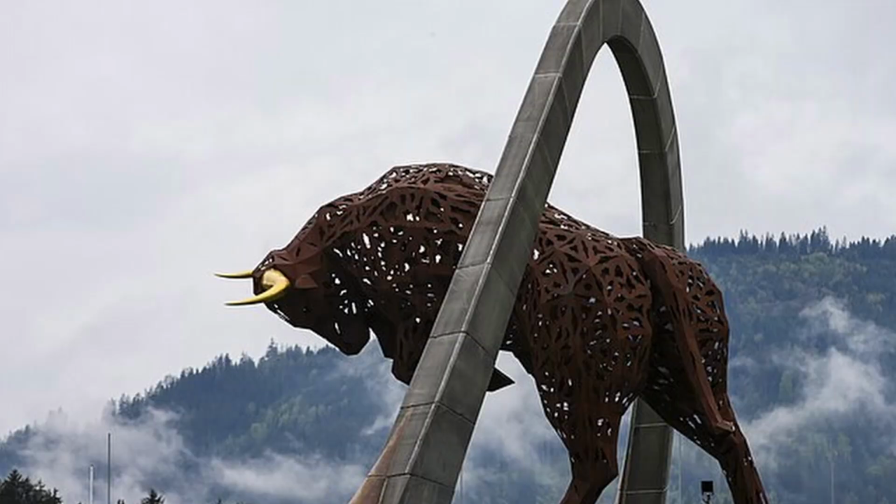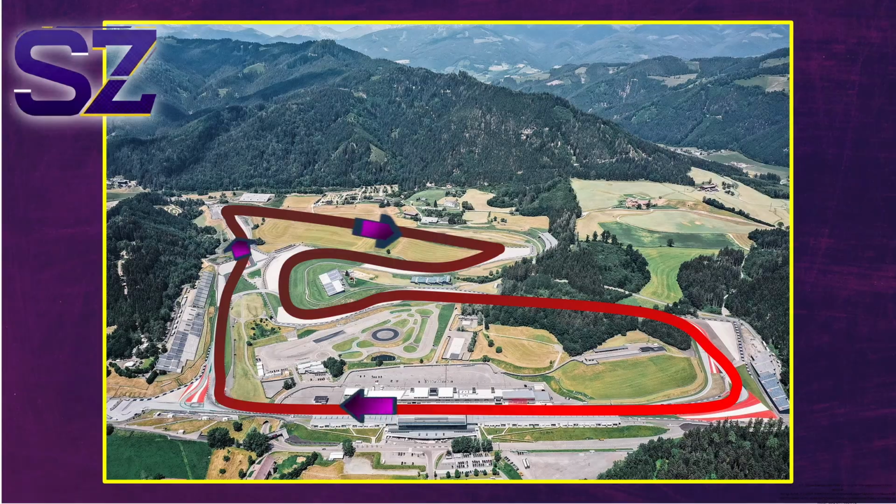The Red Bull Ring is short, just 10 corners, but that doesn't mean that setup is made simple. You have altitude reducing downforce, you've got aggressive curbs testing your suspension geometry, and you have 3 major braking zones that punish weak energy recovery systems or brake ducts.